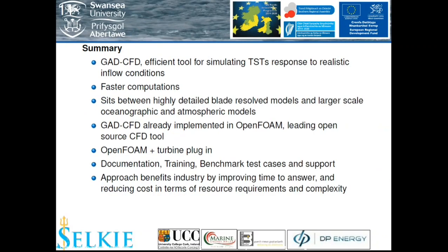Just to summarize, the GAD tool is efficient for simulating tidal stream turbine response to realistic inflow conditions. Model validation has been conducted with GAD-CFD measurements, and due to the computational efficiency of such an approach, especially compared to fully resolved turbine models, GAD-CFD is suitable for modeling arrays consisting of a large number of rotors, and for conducting multiple model runs under varying tidal and machine operating point conditions. The model sits between highly detailed blade resolved models and larger ocean models and atmospheric models.